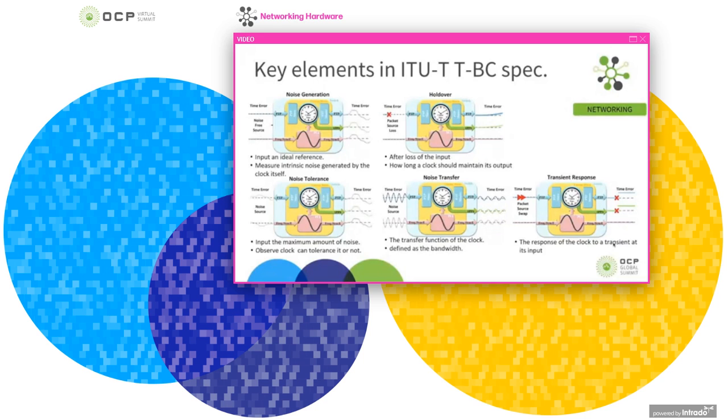So at this time, we must make sure that we can always keep stable timing to the next level, because the boundary clock has an important feature: we have a timing center inside it, so we can retain a stable time even if we do not receive the time source from the master side, so we can keep the system more stable in timing.